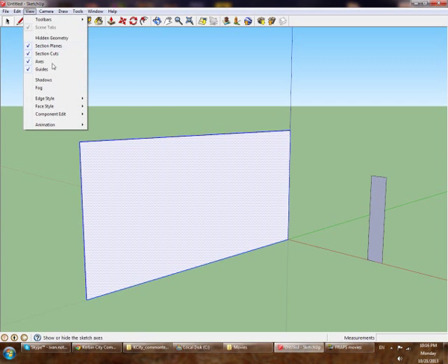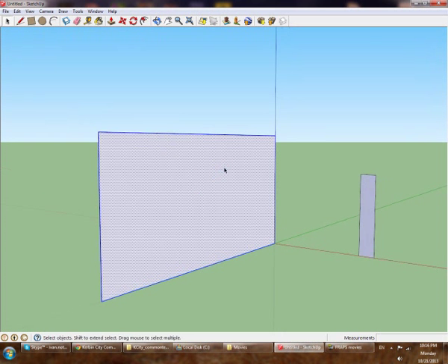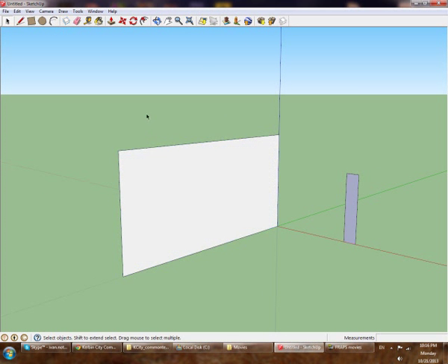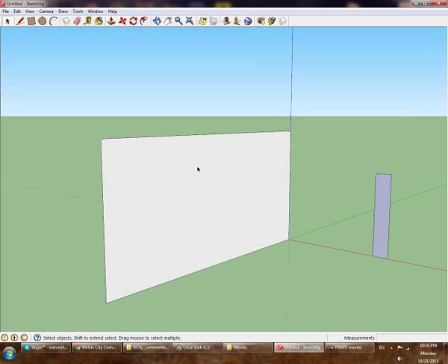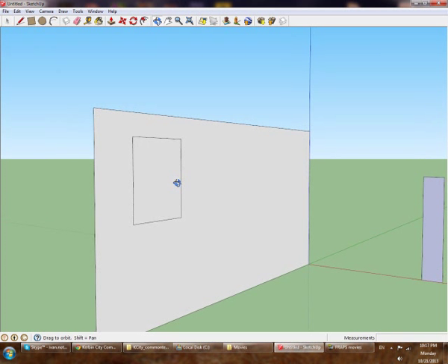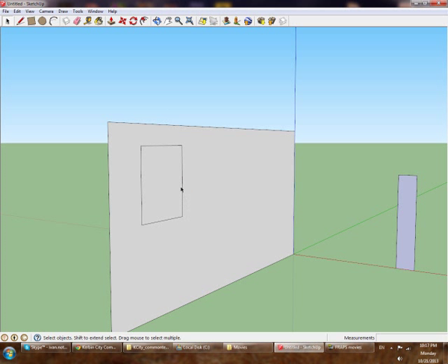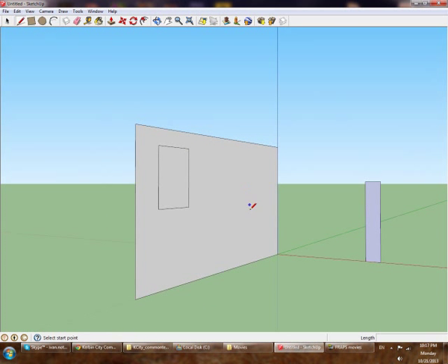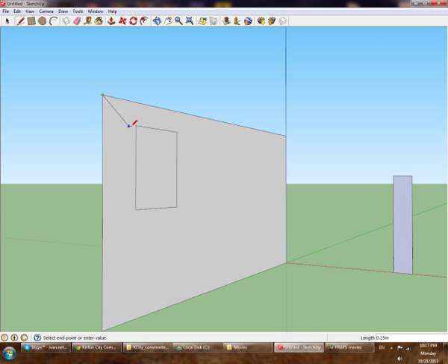I was trying to view inside the views. I thought there is something, but yeah, this is something that you should really know, and this is a big problem when you extrude things in a normal SketchUp way. You draw rectangles. For example, you draw a rectangle, and what happens now is that this rectangle has hidden edges that are actually going from its vertices. So actually, if you would import it into the game, the edges would look like probably something like this, but you can't see those edges in SketchUp.